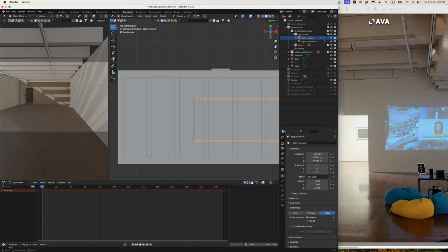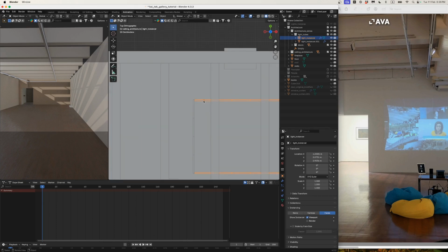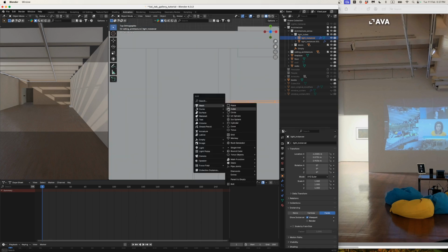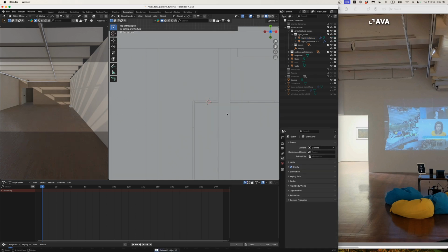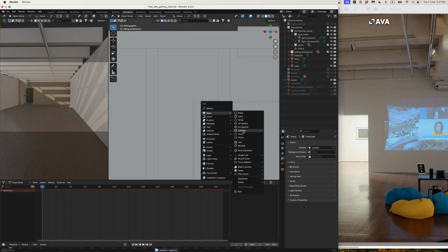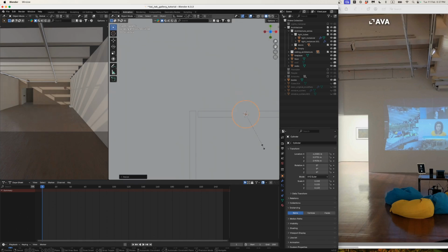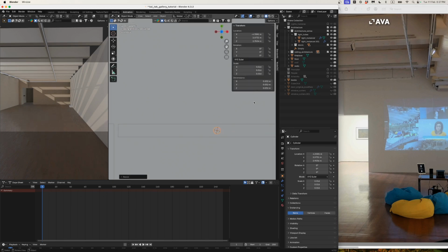So I'm just going to add a little cylinder. First of all, Shift S and put my 3D cursor on what is selected, so I add my cylinder in the same place. Shift A, add mesh, cylinder. Oh, that's not a cylinder. Cylinder, here we go. Scale it down. I think they're pretty thin, something probably like that. We can even check the dimensions. Those threaded rods are probably about maybe 2 centimeters wide, so we can make all of these 0.02.